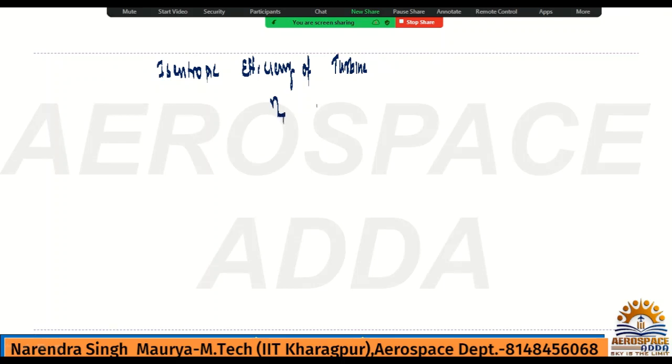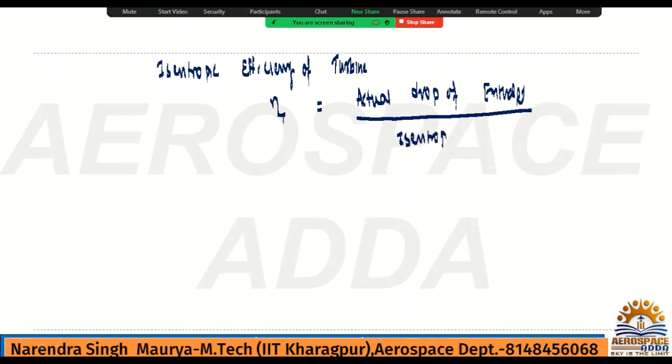Just like for compressor eta C, here we have eta T. It is nothing but actual drop of enthalpy divided by isentropic drop of enthalpy.